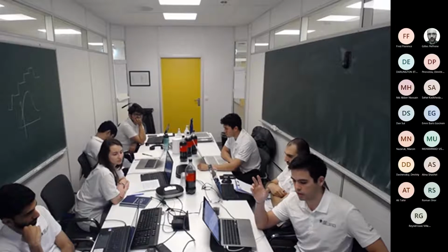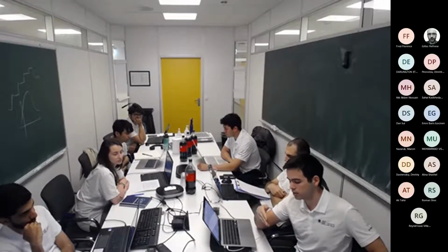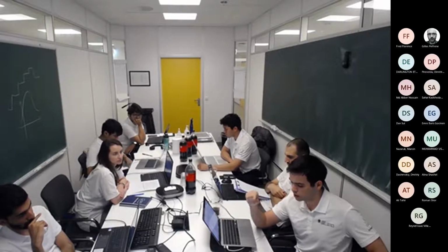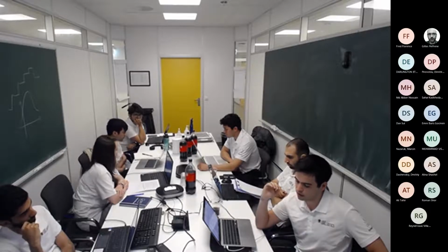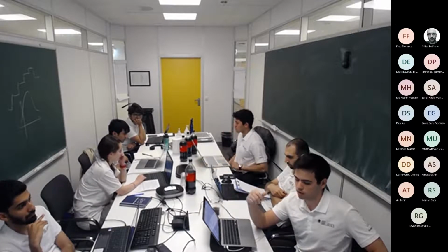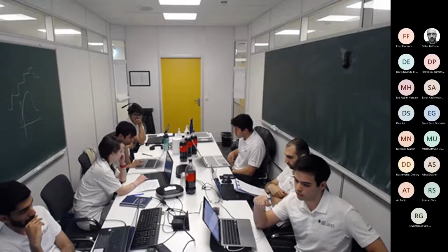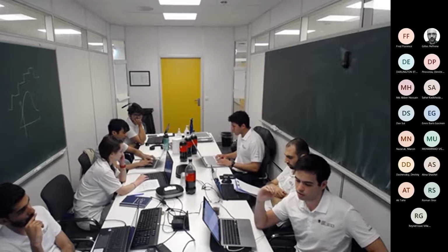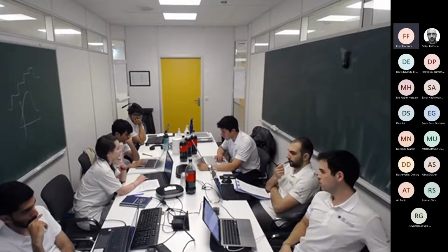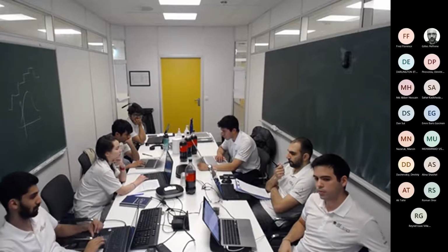all the way up, dividing the drill string into a number of parts, let's say 100. We create 101 nodes. For each node, we calculate the pressure all the way to the top. And when the pressure at the top coincides with the atmospheric pressure, according to a tolerance that can be set as, let's say, 0.1 bar, that's when our iteration finishes, and that's when we stop updating the downhole bottom hole pressure. Okay, and wellbore diameter is bit diameter? Yeah. Okay.